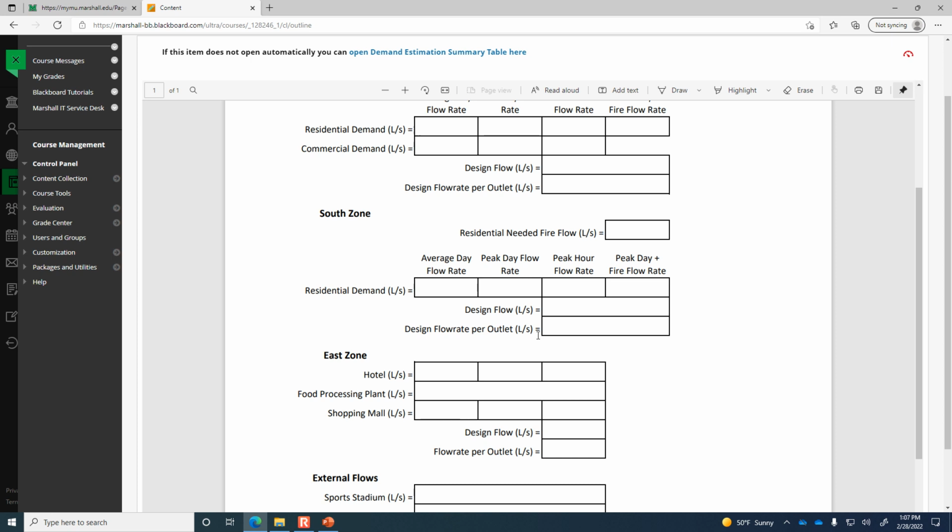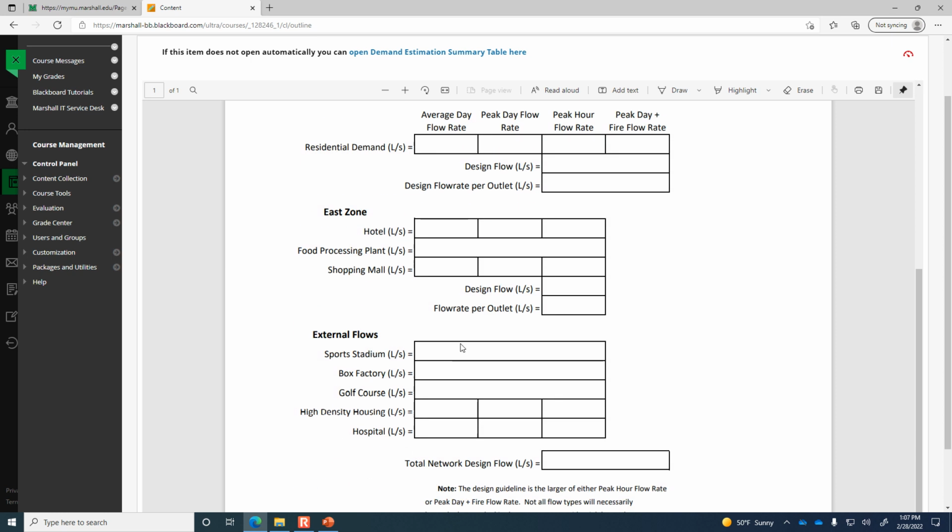And you also need to think a little bit about irrigation of the golf course. In the past, students have said, well, if the depth that you have to apply to the golf course is half an inch, and you multiply it by the area of the golf course, you're going to find a certain volume. Some people have divided that volume of water by 24 hours a day times 3,600 seconds per hour. And so that's non-conservative, and also it would be a nuisance to the golfers.